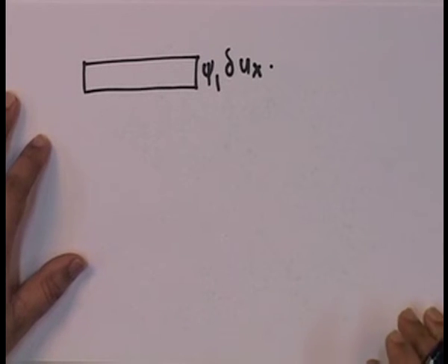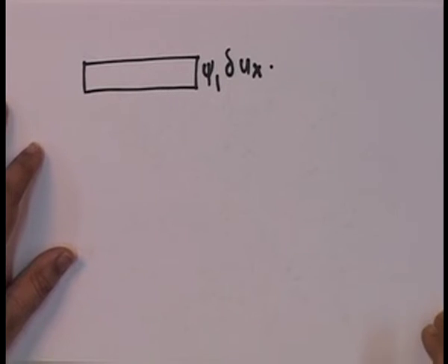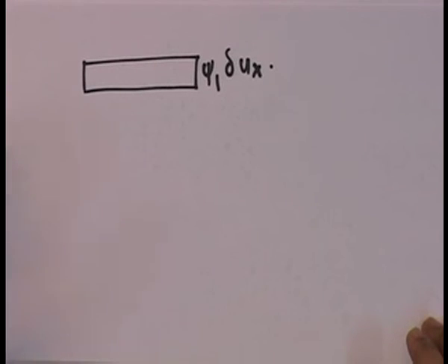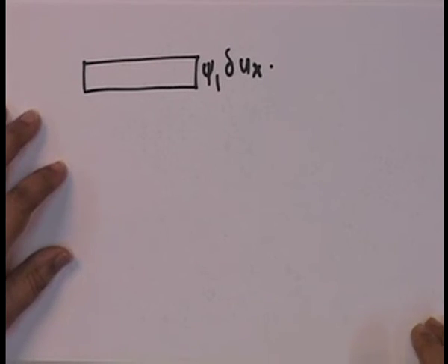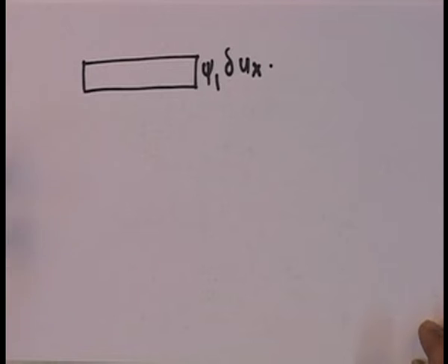And all I have to do for getting two equations is write down virtual work equations for two different, linearly independent displacements. And since my degrees of freedom are independent, I always take displacements that correspond to the degree of freedom, because I know that they are independent. Then I can get two independent equations.